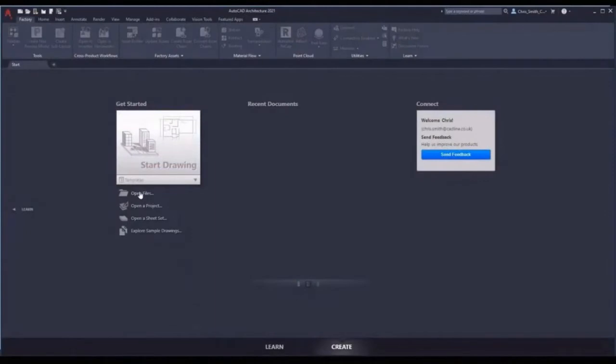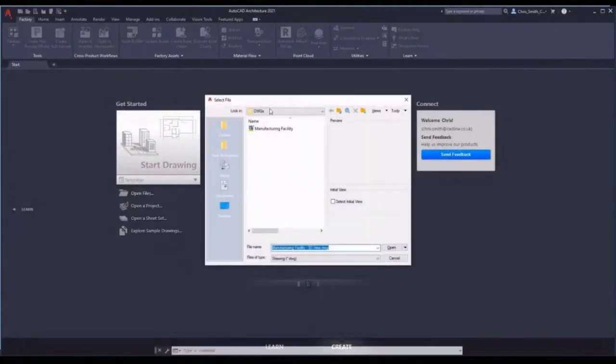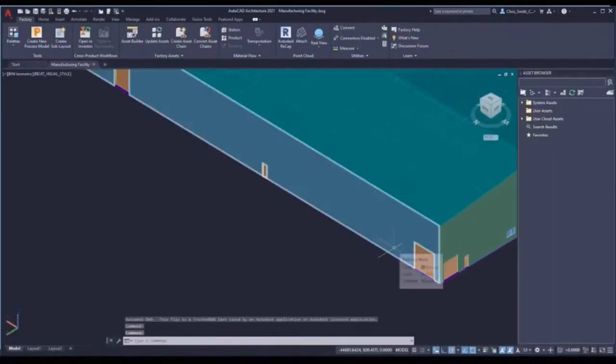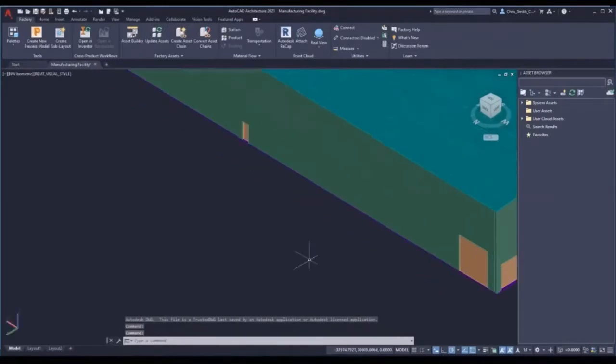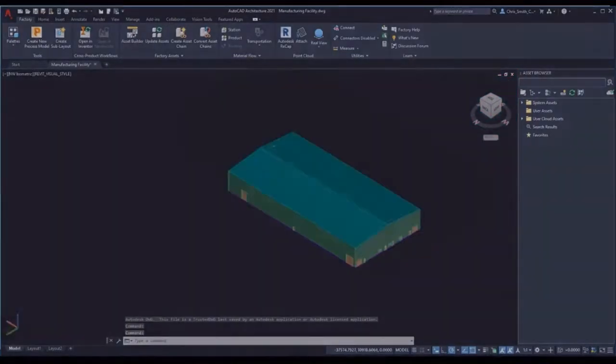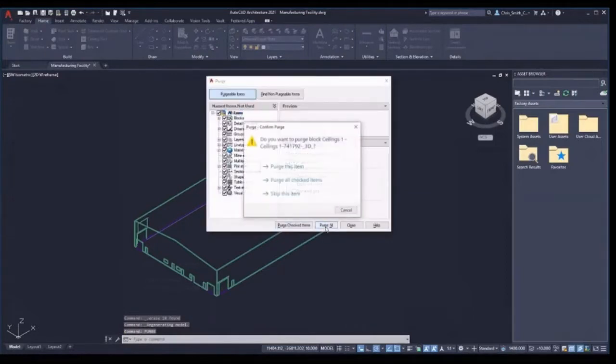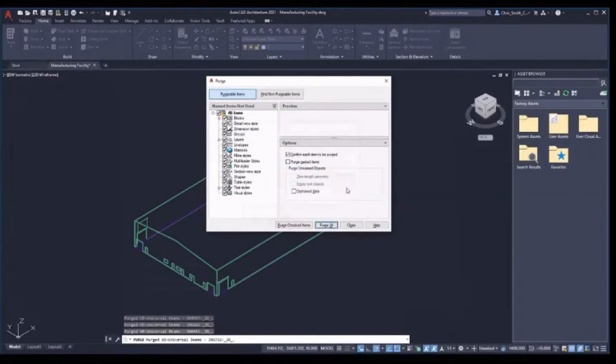Now we have our 3D DWG file, we can go ahead and open this file in AutoCAD Architecture. From here, we will need to modify the data we've been given, as there may be information in the file that is no use to us and could hinder our ability to work optimally. Once the delete operation has completed, we can follow this with a purge command to completely remove all the unused data within the file. Then we unfreeze our wall and floor layers, ready for the next step.